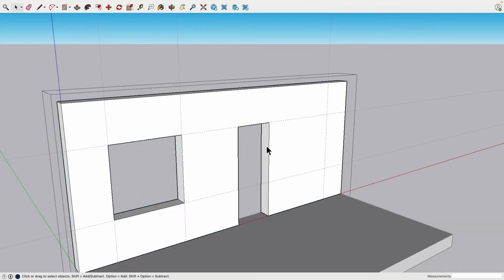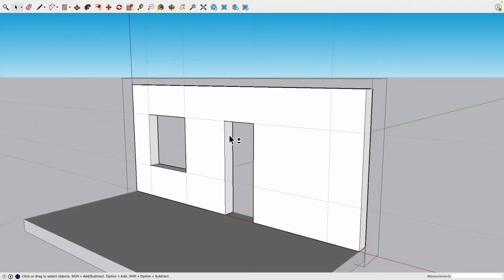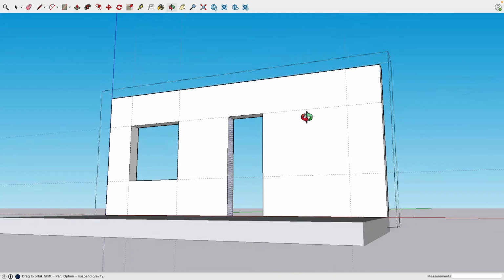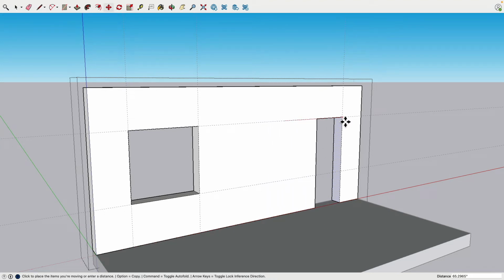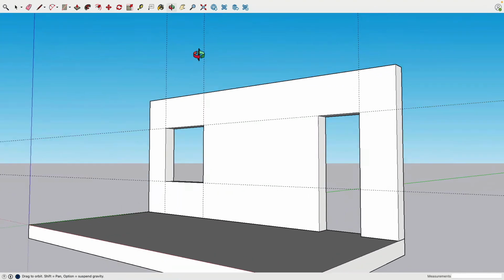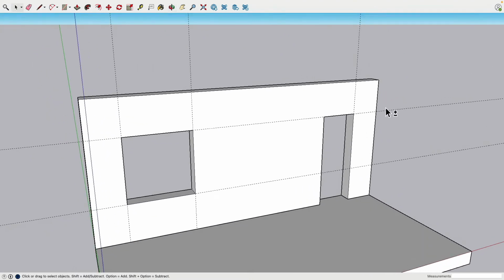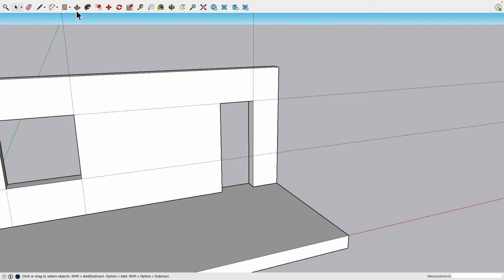And then how can I move the whole thing? One very easy way: I go into edit mode for this group and select the left and the right face. That's all I need. Then I go to the move command, move this over along this guideline, and snap it to there. Click, done. Easy peasy. Okay. I could have pushed and pulled each face too, but as you see, I just selected the faces and moved the whole hole at once.